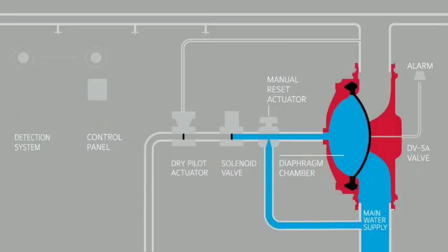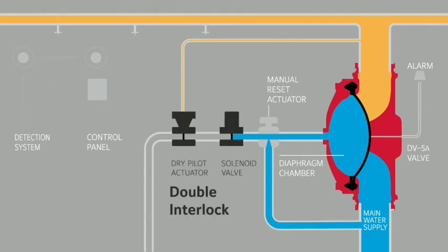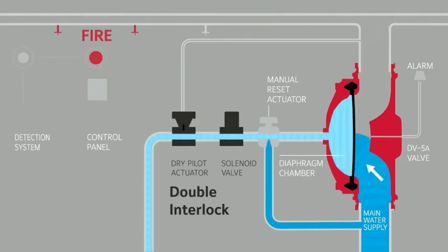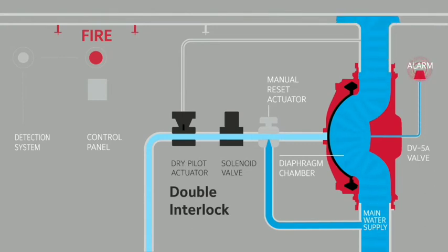Solenoids, electrically actuated directional control valves, form the interface between the two parts of an electro-pneumatic control. The most important tasks of electrically actuated DCVs include switching supply air on or off, and extension and retraction of cylinder drives. Electrically actuated directional control valves are switched with the aid of solenoids. They can be divided into two groups. Spring return valves only remain in the actuated position as long as current flows through the solenoid. Double solenoid valves retain the last switched position even when no current flows through the solenoid.